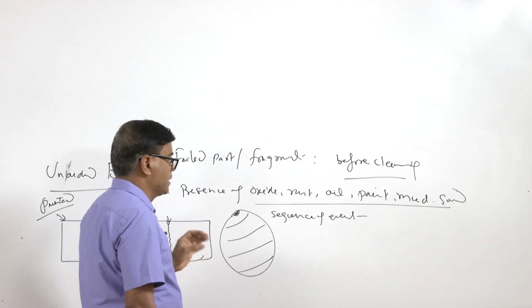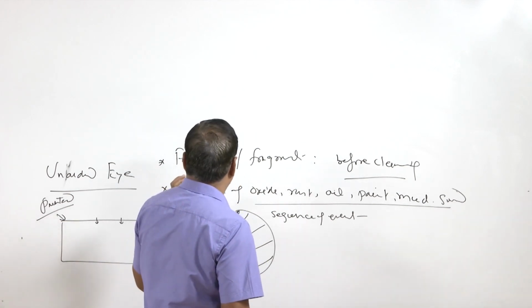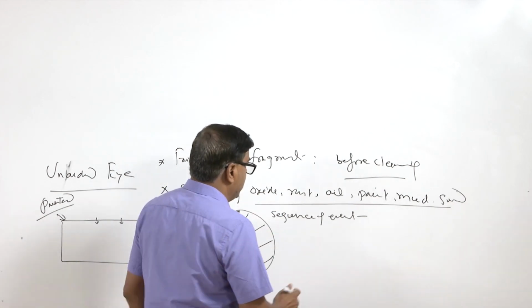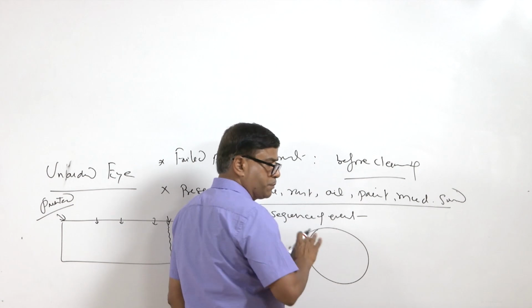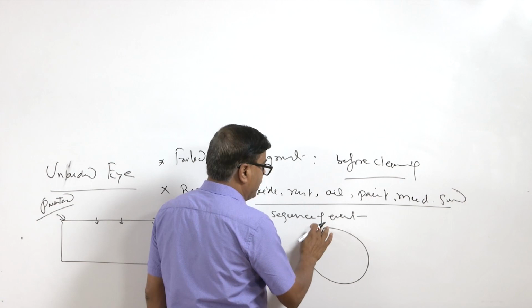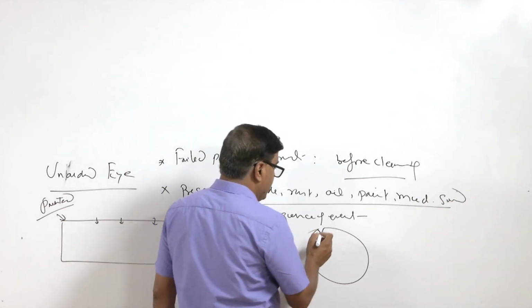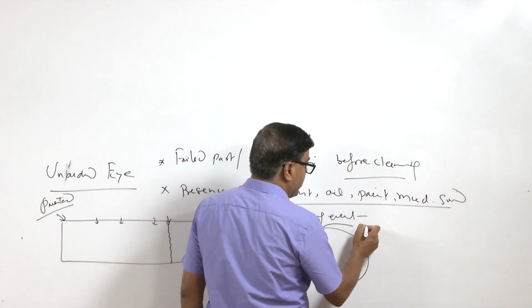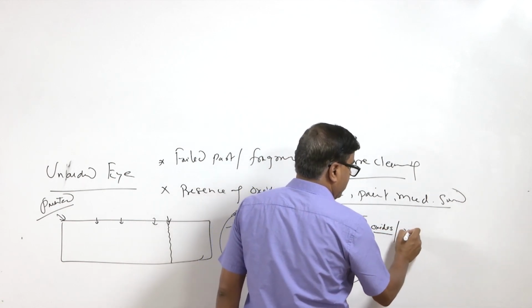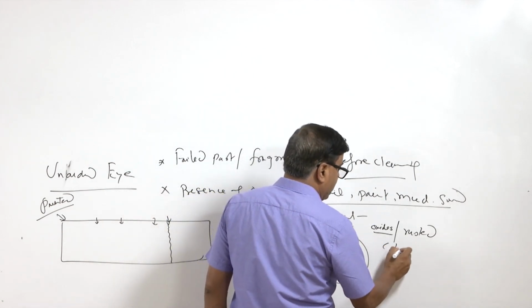So, it will indicate that the crack was present since long, and it has grown gradually under the service conditions. In addition to this, there is one more way of relating these things with the failure. If a steel component was exposed in normal ambient conditions, and it had discontinuities in the form of pores or cracks, then the surface which is exposed will get oxidized, will have oxides, or will get rusted. So, of course, it will have a different color.